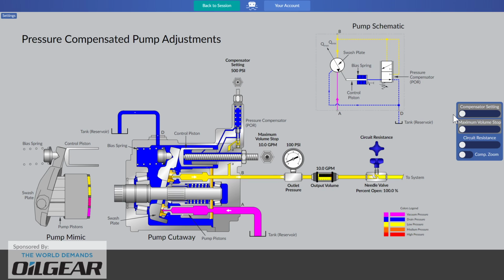And if I said, hey, maybe our pump pressure compensator shouldn't be at that level, or perhaps there should be a different pressure, perhaps set it to 700. And if I went over here to the controls on the right-hand side of the screen and I started moving them around, and perhaps someone would argue that now I'm set to, let's set it to around 750, somewhere close to that. There we are, set at 750. You might say, hey, how do you know that? Well, in this case, only magic text here above the simulation, so that's not realistic.